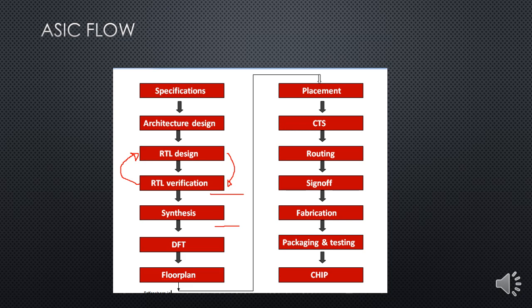But here, the DFT, design for testability. This is the one step where the DFT engineer will add some code into my design, so that once the chip is fabricated, we can test that particular chip. Whatever IC is fabricated has to be tested first.